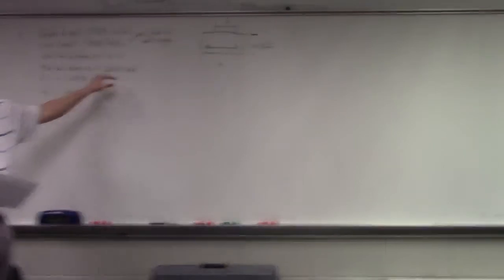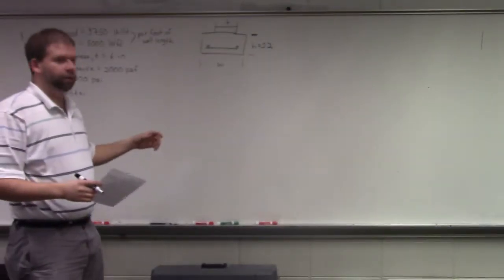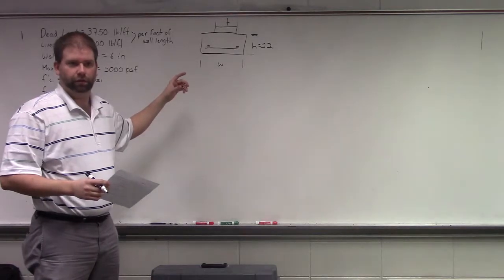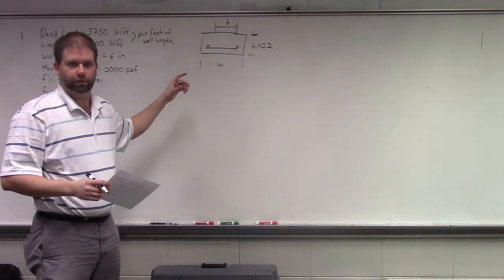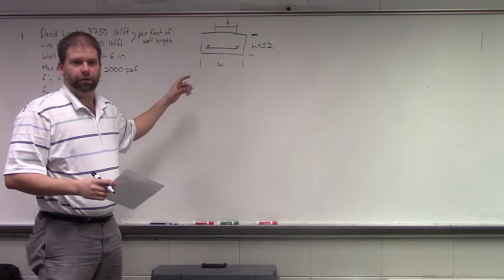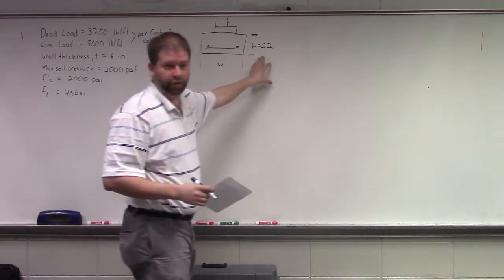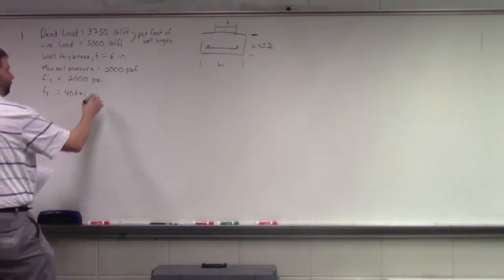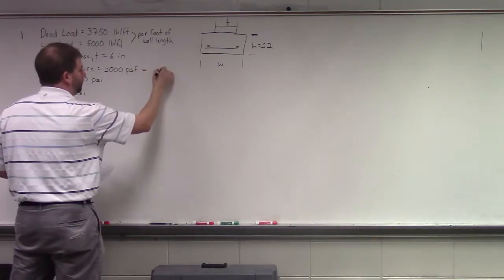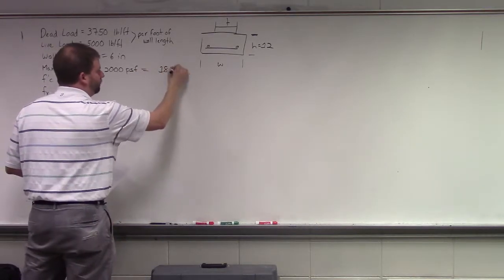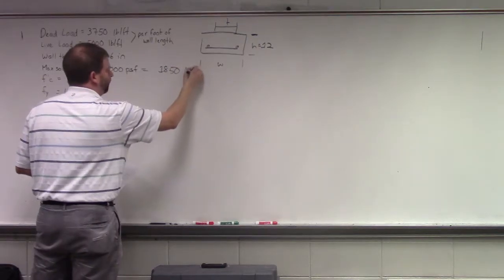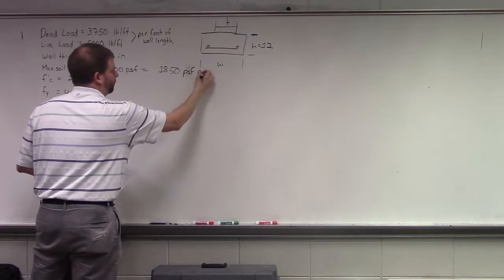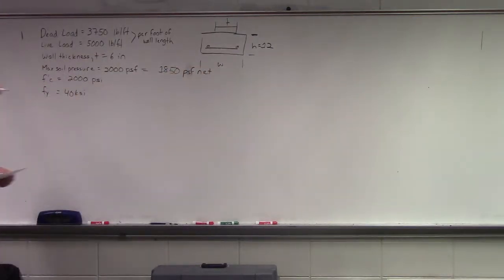If the concrete's 150 pounds per foot, then we take 2,000 minus the 150, because it's 1 foot, so you get 1,850. That's what worked out well for that 12 inches, it changed it to 150 pounds per square foot. So this became 1,850 pounds per square foot net.